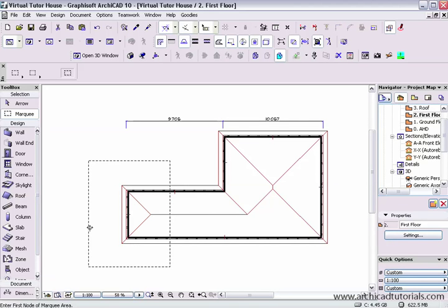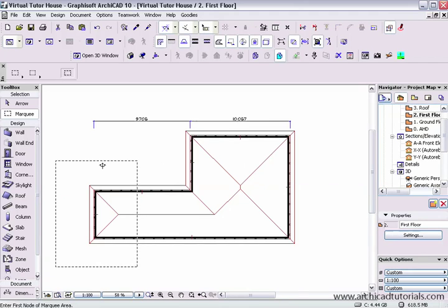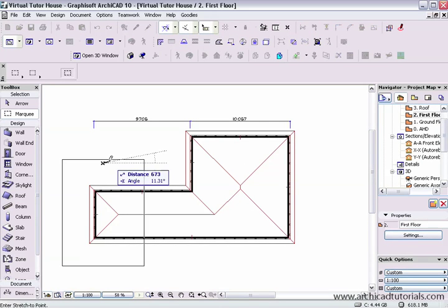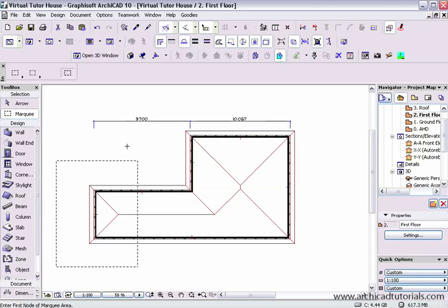So if you wanted to move your building and stretch elements in your building on all floors, you would use the double marching ants, and if it's just a single floor, you'd use a single row of marching ants. Then we need to make sure that the grouping is off or suspended. So I just push Control H, left mouse click once, move that way until a guide comes up, and I'm just going to type 5mm, and we can see that now that's a nice round figure.